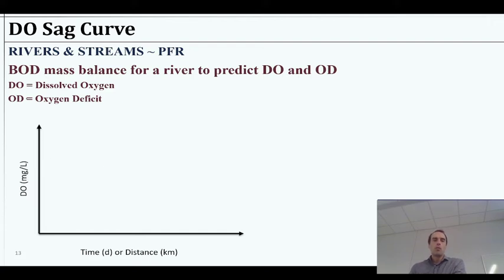Really, what we'll notice is the oxygen sag curve, as we'll call it, is in relevance to some saturation point. So we have, based on temperature and stuff, the DO saturation is up here. And natural river water typically is not quite saturated. There's usually some biological activity happening.